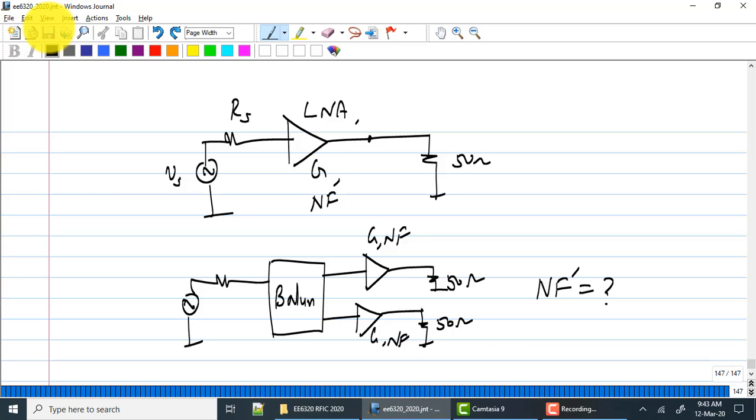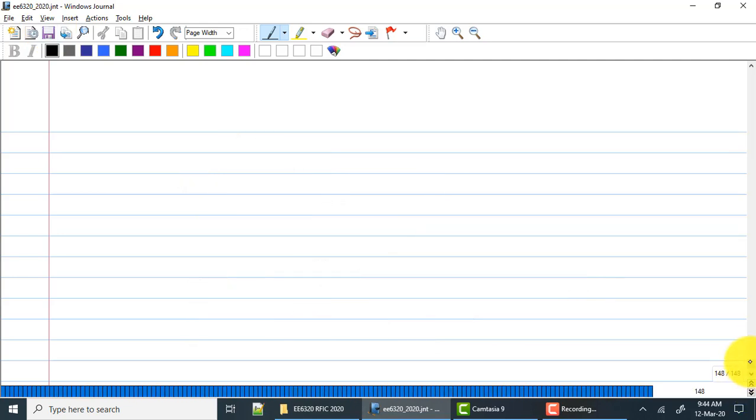What are the S parameters of an ideal balun? I have a 3-port network. There are many different ways to create an ideal balun. If you don't want to use any of the ones, you create an N port. In our case, it's a 3-port. So connect the reference to ground, port 1, port 2, port 3.